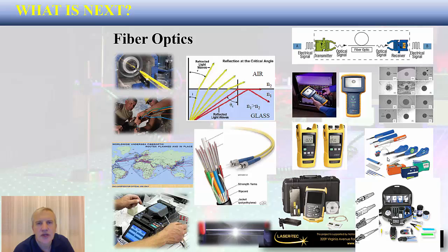The fiber optics course focuses on the aspect of the optical fiber. In this course, you're going to learn about optical fibers, what they're made out of, and also how they're being used. You're also going to learn how to install the connector on the optical fiber, how to do the fusion splicing, and also how to perform different types of measurements, including the tier 1 measurement using OLTS, and also tier 2 using optical time domain reflectometer, or popularly known as OTDR.